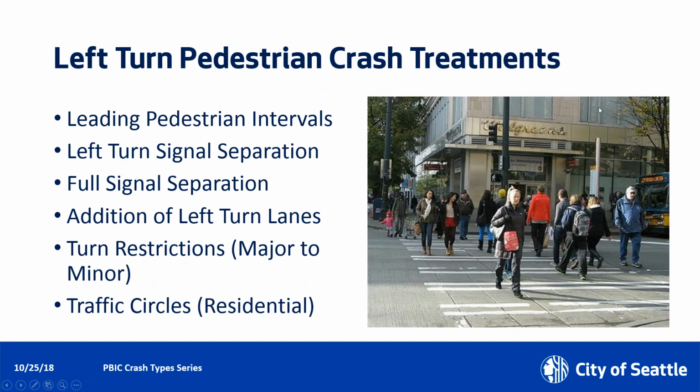So there's a few different types of treatment methods that we can use to reduce crashes in different environments. I'll go over all of these in greater detail, but similar to what Chris and David mentioned earlier, leading pedestrian intervals and left turn signal separation are great treatments to reduce that exposure. You could even go as far as full signal separation, where you have completely isolated signal PED phases from vehicular phases, and then getting into some uncontrolled intersection treatments, just the addition of left turn lanes or turn restrictions, or even in a residential context, using traffic circles has a benefit for pedestrians and left turn crashes.